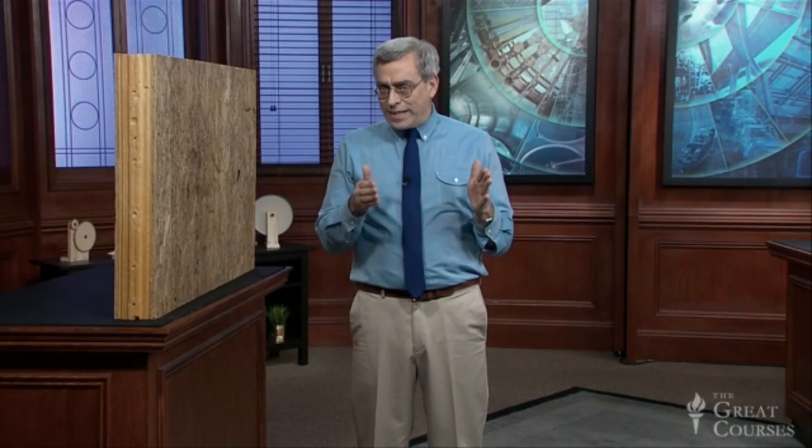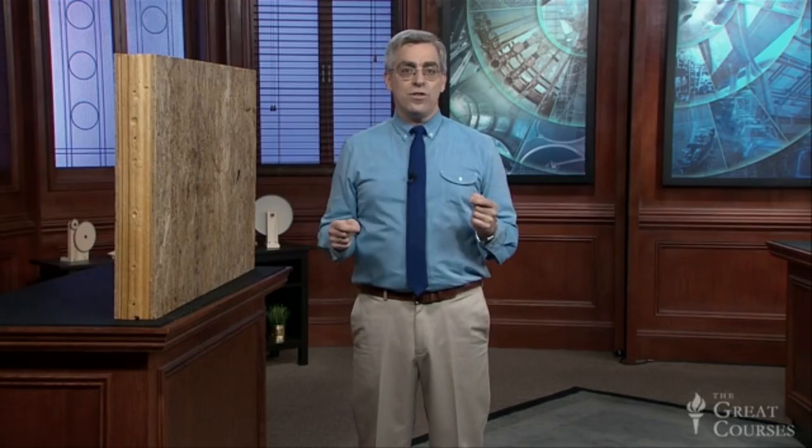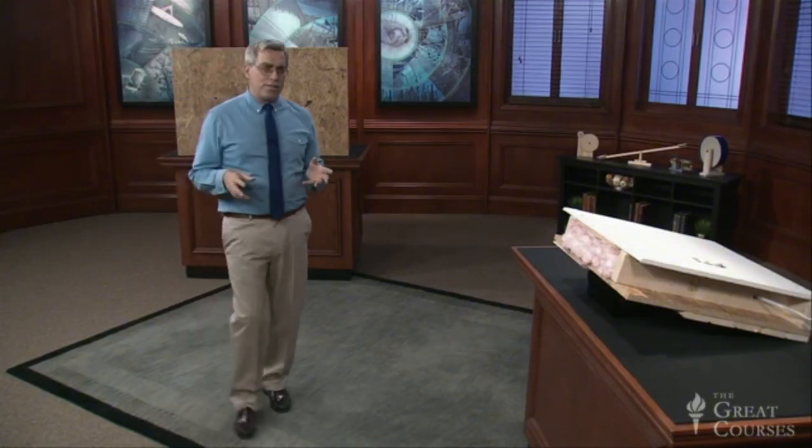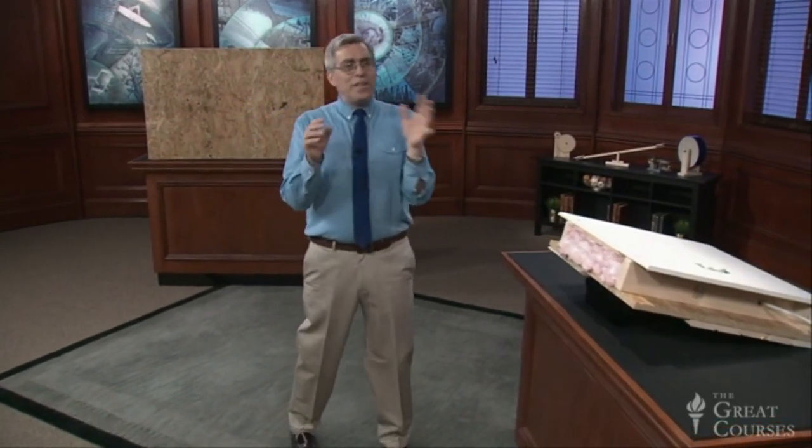Second, as we saw in the last lecture, forced air heating systems can cause similar pressure imbalances and similar movements of air through the building envelope. And third, within your home, hot air rises and eventually finds its way into the unheated attic space through gaps around light fixtures, attic access hatches, and such. And as the warm air escapes from the top of the building envelope, cold air seeps in somewhere below to replace it. Given these causes, minimizing air infiltration is simple in concept, but very challenging in practice.